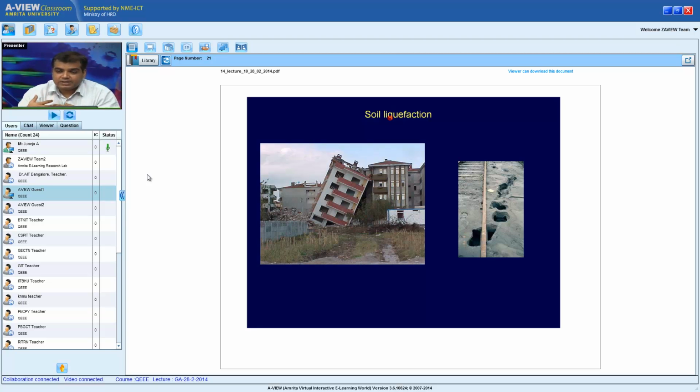Even if you are using sand, a very permeable soil, the loading is done in a fraction of a second, or maybe lasts a few seconds, but that loading is tremendously high within a very small time, and that induces an undrained condition. So your pore water is not able to escape.